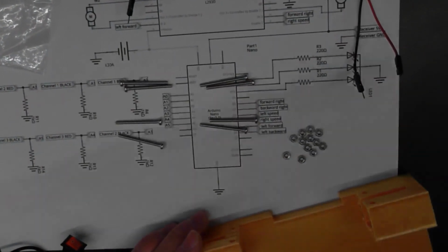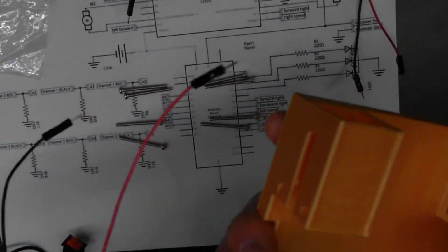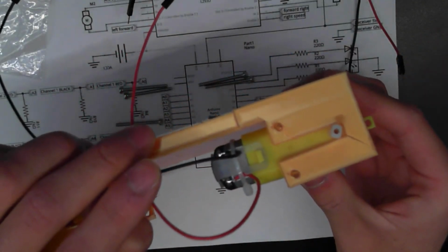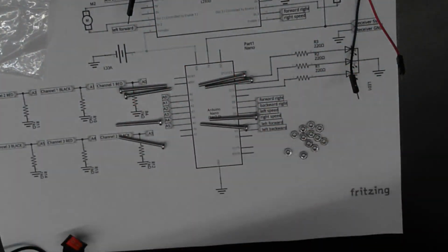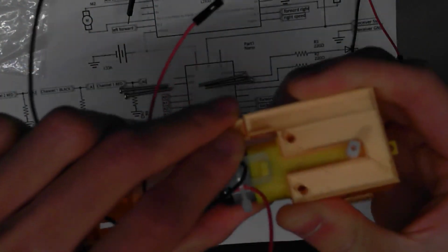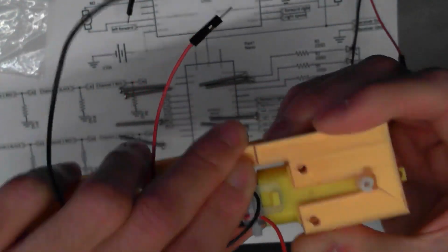So grab a gearbox, like this one, and I would suggest pointing the wires outward so they can wrap around to the top because that's where they'll be going. And slide them in such that the white axle points outward and slides through here, just like that. And once they're seated fully in, you should be able to see a hole here going through, and that's where you can send in your bolts. It doesn't matter which side you send it through, just as long as it's secured well.